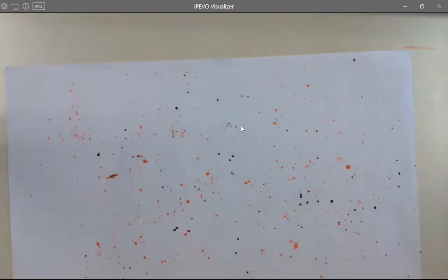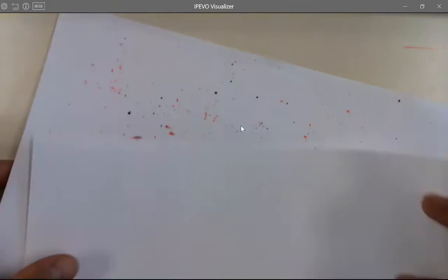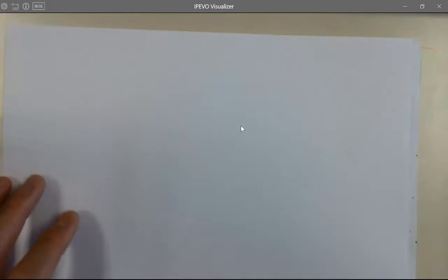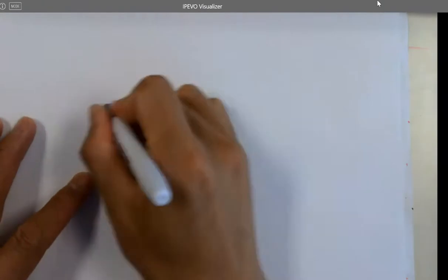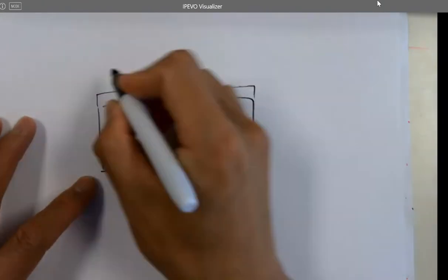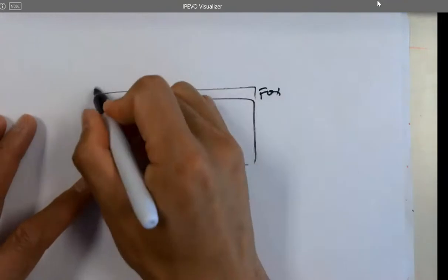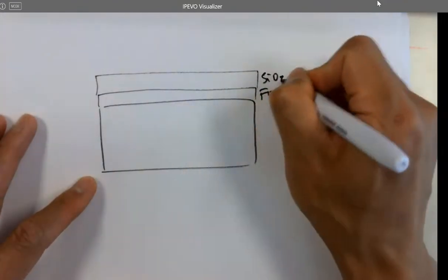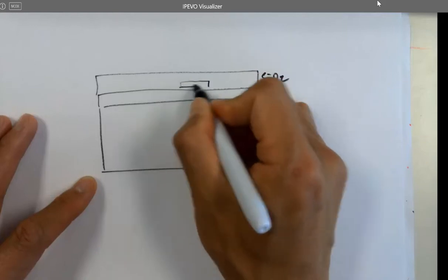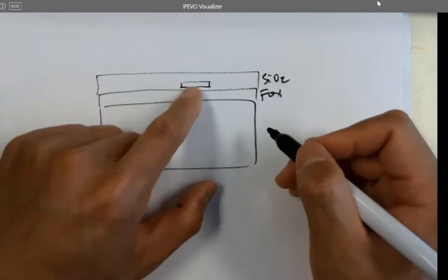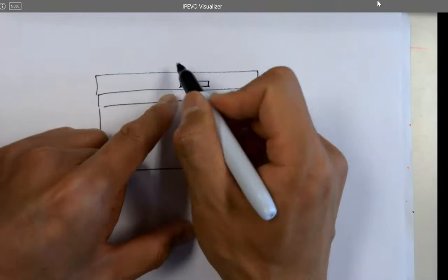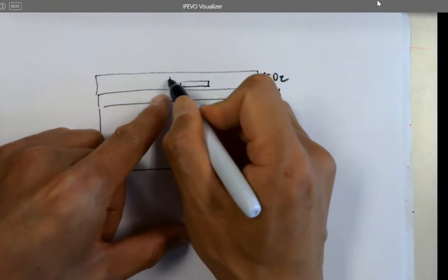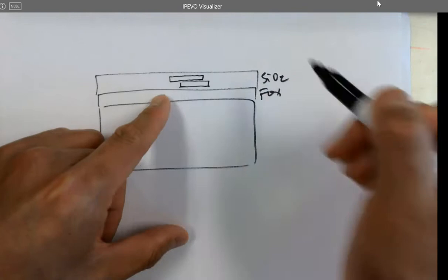If you are just drawing a CMOS transistor, you can see all the pink traces are poly 1. But there's a poly 2. There are two poly layers. But you don't have to draw that. Keep in mind, you don't have to draw that, unless you are making a capacitor. Here's the poly layer. Here's poly 1. As there's no connection, it's actually not at the very bottom. Interesting. But you can draw it to the bottom, which is fine. It's just showing you that you don't have to. So there are two poly layers you can make.